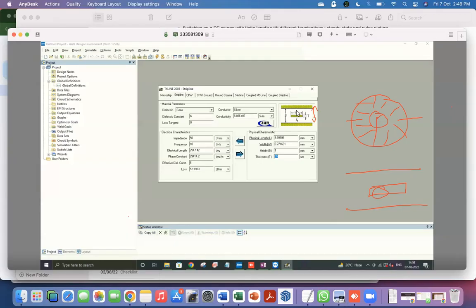Last time I had circulated those boards, so they are from a specific company. This is a specific model, has a specific dielectric constant and thickness of the copper coating on it. These are things you specify when you buy this circuit board from the company. So that's why the calculation only changes the width, because that's really the only design parameter you have in your control.